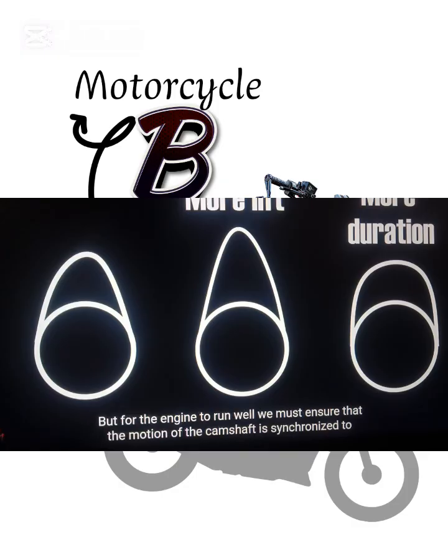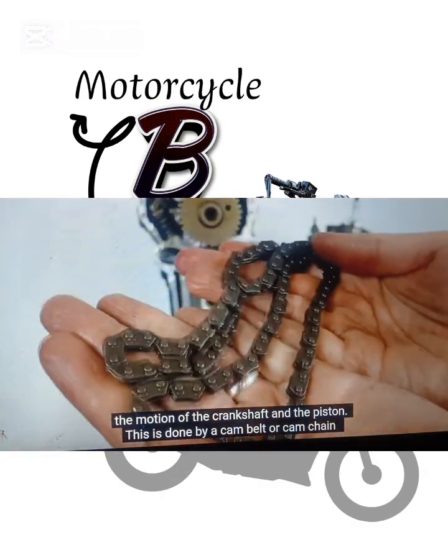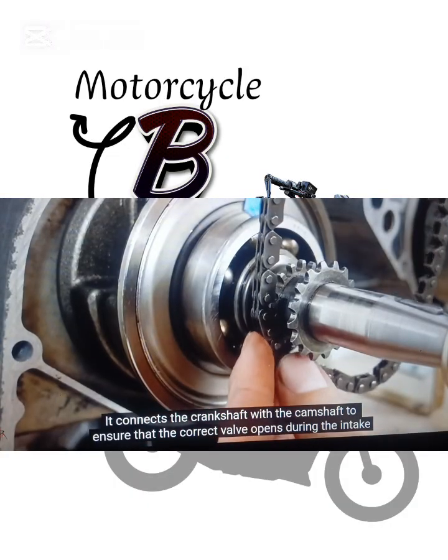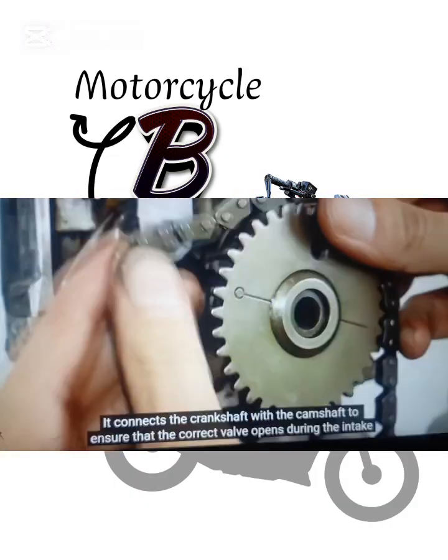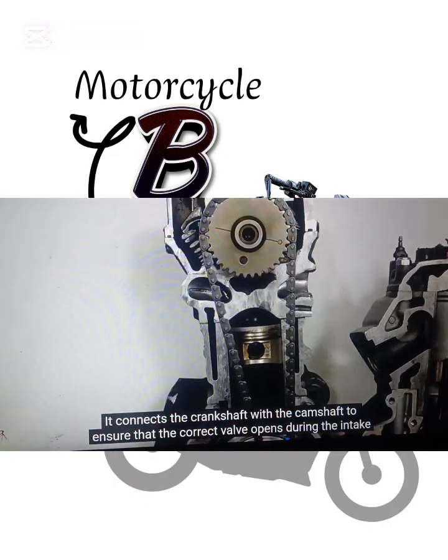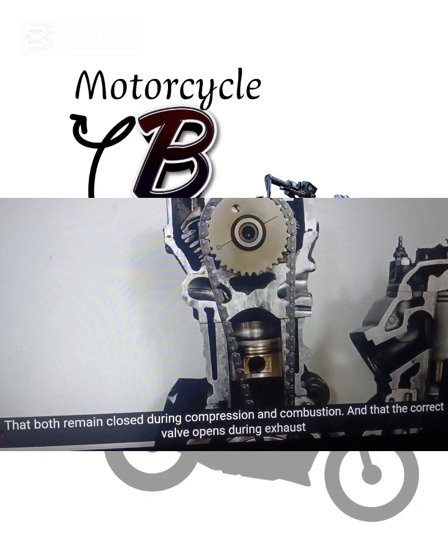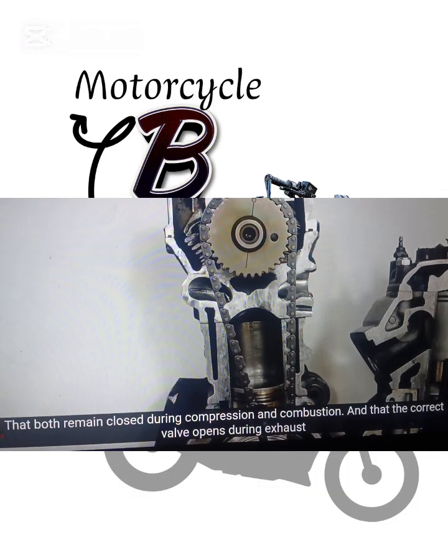But for the engine to run well, we must ensure that the motion of the camshaft is synchronized to the motion of the crankshaft and the piston. This is done by a cam belt or cam chain. It connects the crankshaft with the camshaft to ensure that the correct valve opens during the intake, that both remain closed during compression and combustion, and that the correct valve opens during exhaust.